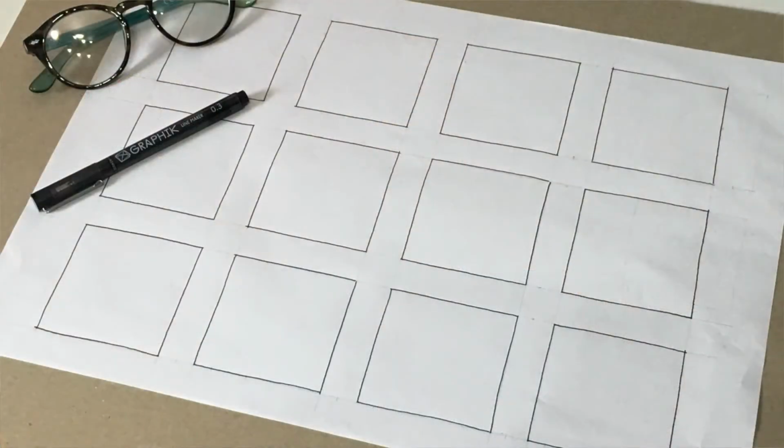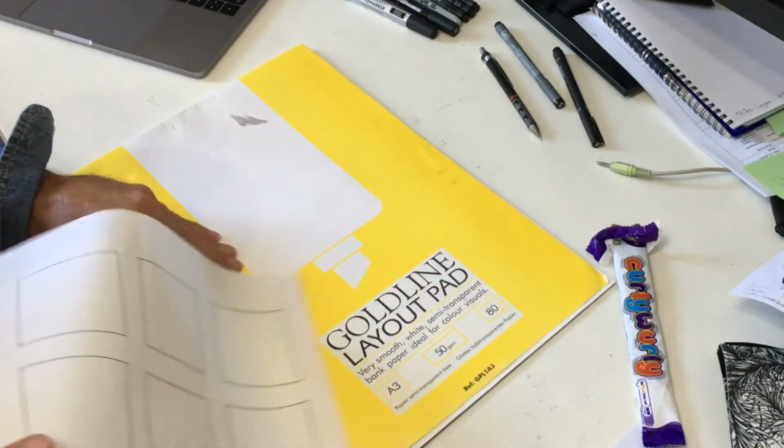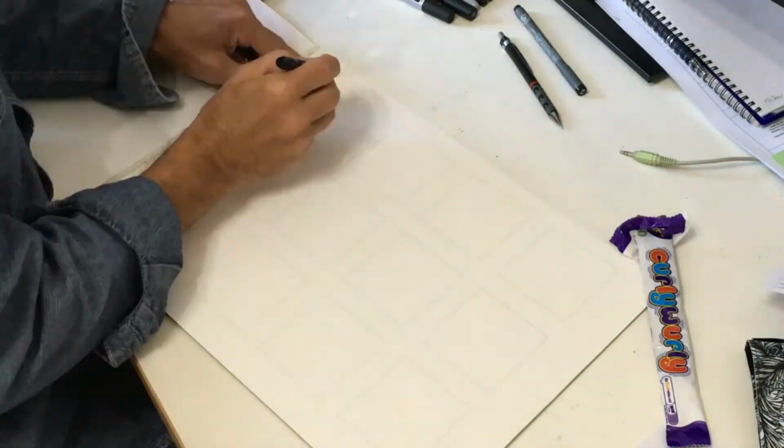This is what I need you to do. On an A3 landscape sheet of paper, draw 3 rows of 4 boxes 7 cm square, leaving approximately a 2 cm gutter between them. You need space so that the drawings don't interfere with each other. Your master template should look something like this. Don't draw on the sheet, but use it as a master to trace off the squares so you don't have to measure each time you start a new sheet.